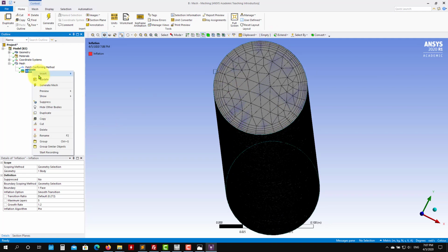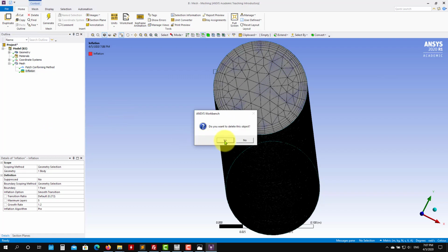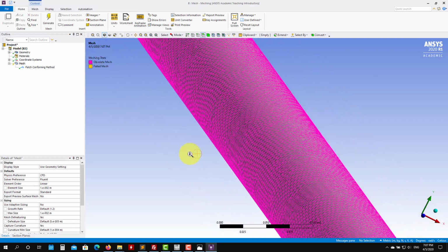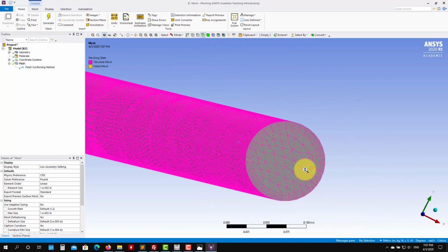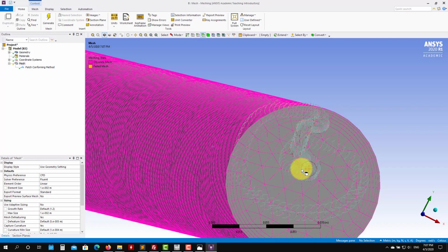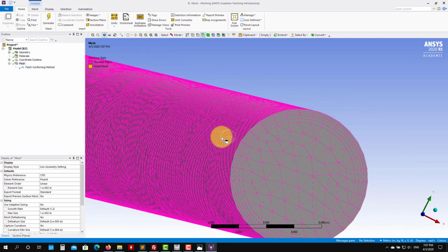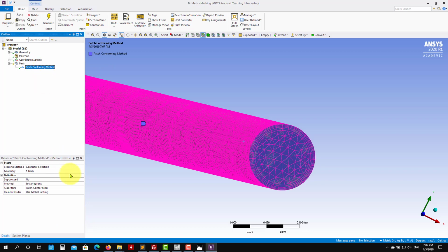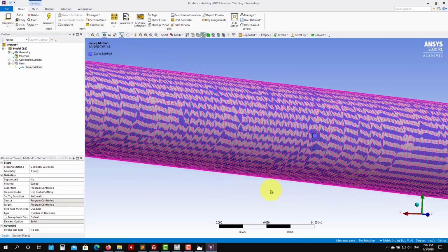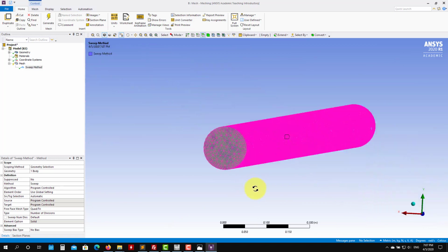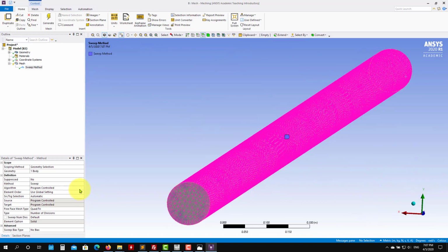So let's go here, let me erase this one, okay, because I want to use another option. I can do a sweep, okay, sweep like the one with the extrusion in the geometry. We can mesh a face and then do an extrusion of that one, okay. So the sweep, you go back here. Instead of this one, select sweep, okay? And see that in sweep, you have many options, okay? So let's choose here. I want to have triangular face, okay?